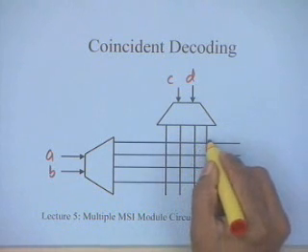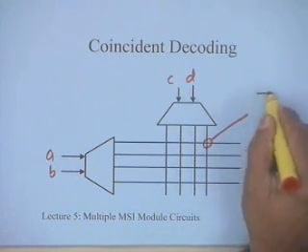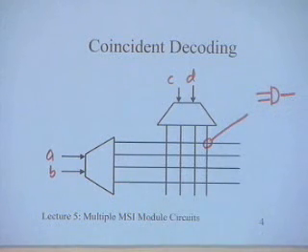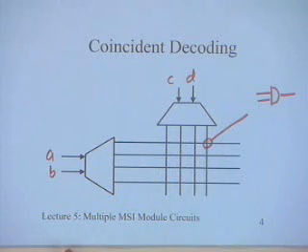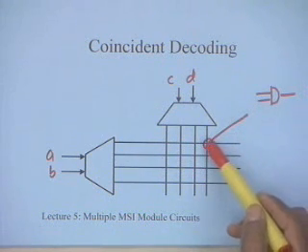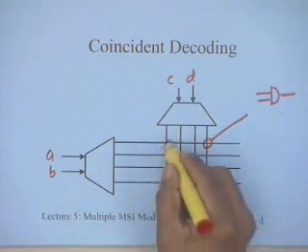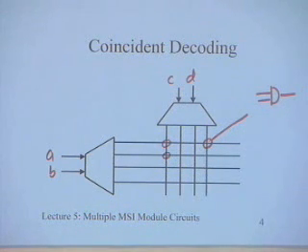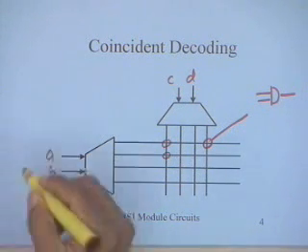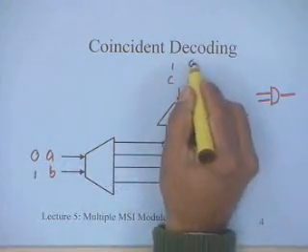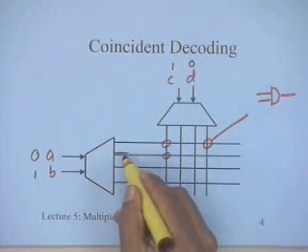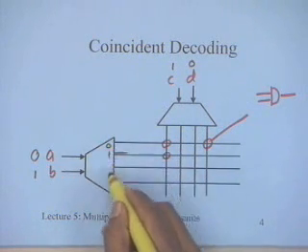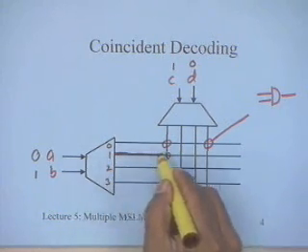The logic I require is, if you consider each of these intersections, each of these intersections is an AND gate. So I have 16 AND gates over here, corresponding to decoding each one of these intersection points. So what happens is, let us say in this case I had to do 0 1 and 1 0. So 0 1 is going to make this particular row, this corresponds to 0 1 2 3, and this particular row will be active.